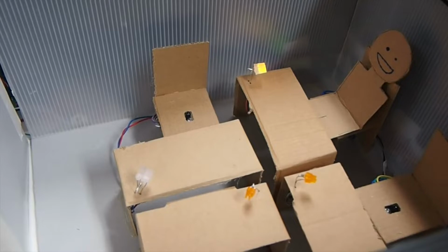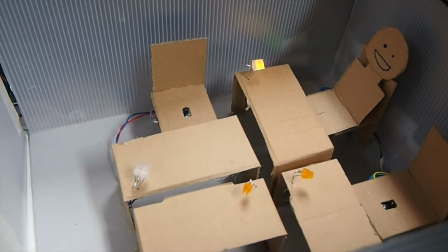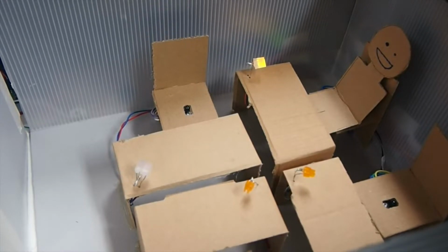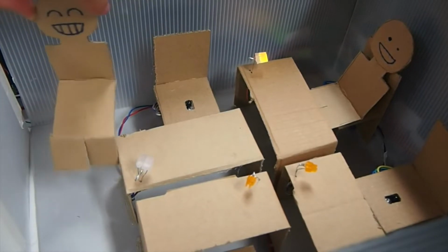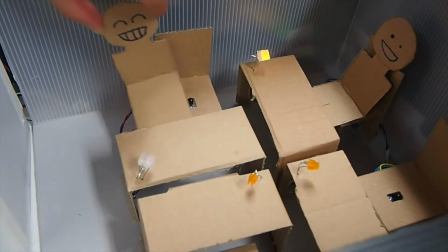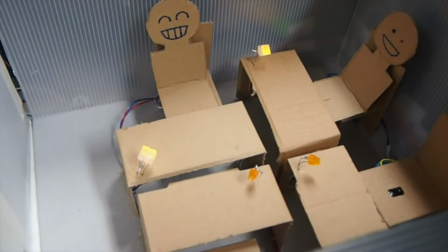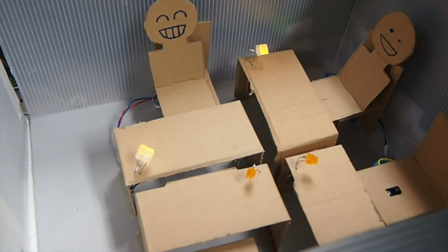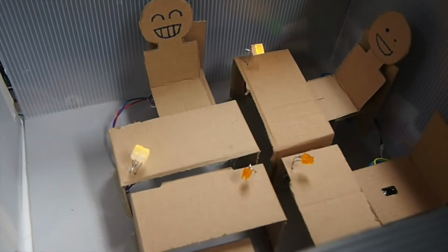If there is someone on the seat, the infrared emitted will be reflected, and the receiver will detect the reflected infrared light and generate a voltage level inversely proportional to the reflected light intensity. When the intensity exceeds the threshold, the STM32F1 will receive a low signal. The STM32 will then charge the gate of an N-MOSFET and it will turn on the LED.